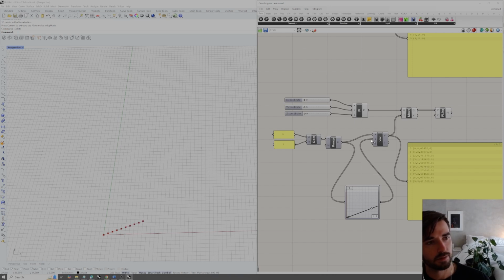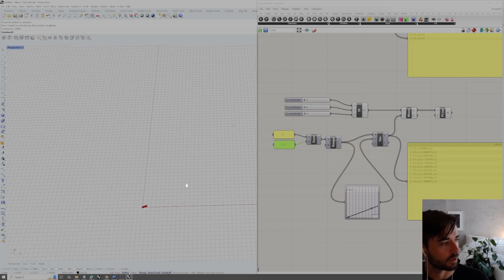And we see something quite strange going on here. What we might have expected is that whatever this slope is, we would see some kind of multiplier of this slope value to the x. What's going on is that it's taking an input of x from 0 to 1, but our domain here is set from 0 to 9. So we want our range here to fit within that 0 to 1 range, so 0 to 0.9, and then we can keep our number of steps at 9 so that we still have 10 values being constructed.